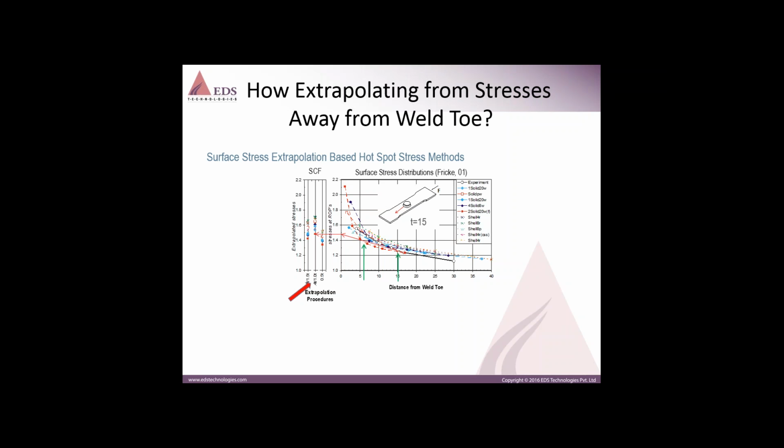So we can connect these two dots with a line, and if we refer to the diagram, we will find the stress concentration factors, and we can read out these values as you can see. The problem, as you can see here, if you look at different procedures, is that no procedure creates an identical value for the stress concentration factor. Not only that, but there is intense scatter. This is one reason why this is not a precise method.